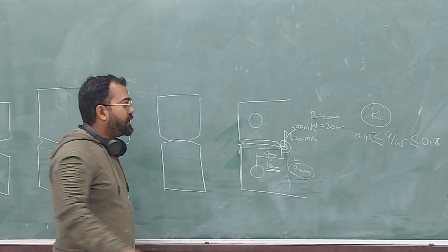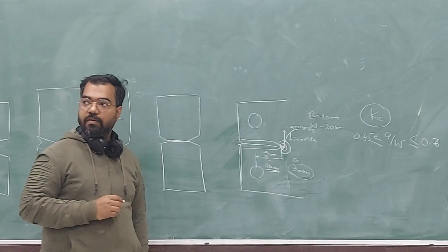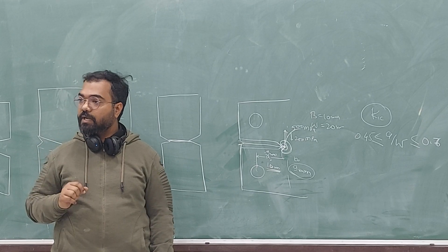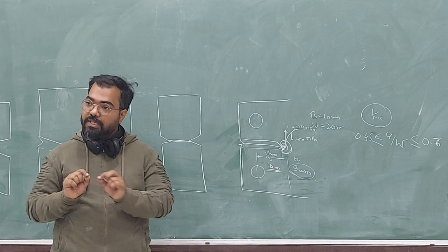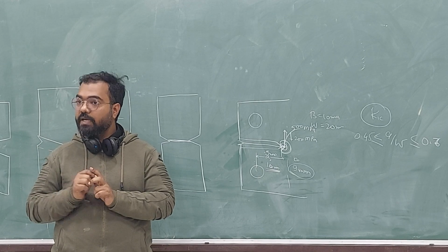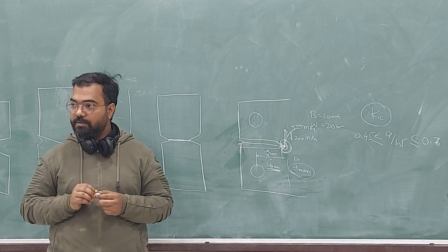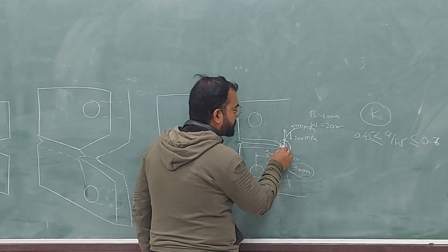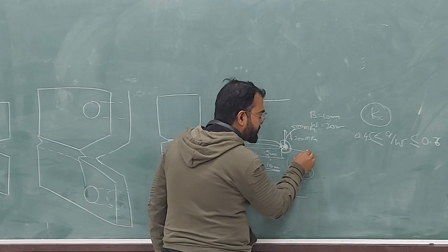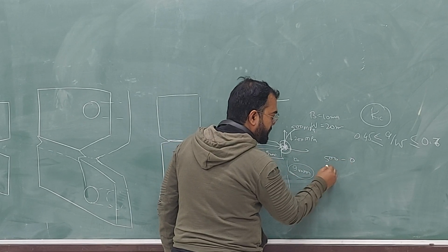Right? So suppose in the first cycle you create a plastic zone, okay? And suppose now that the material has a yield strength of 500 megapascal. So what will happen? You have just created a plastic zone, right? It has crossed 500. It has just achieved 500. So you have a plastic zone. Then you come back to 200. What will happen? You will have another area which needs to plastically deform, and this deformation will be happening at the next yield point, right?